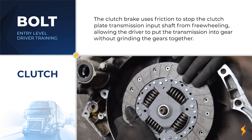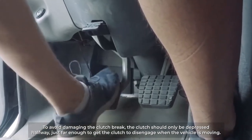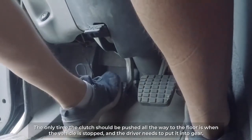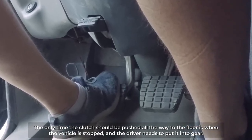The clutch brake uses friction to stop the clutch plate and transmission input shaft from freewheeling, allowing the driver to put the truck into gear without having to grind or force the gears together. To avoid damaging the clutch brake, the clutch should only be depressed halfway, just far enough to get the clutch to disengage when the vehicle is moving. The only time it should be pushed all the way to the floor is when the vehicle is stopped and the driver needs to put the vehicle into gear.